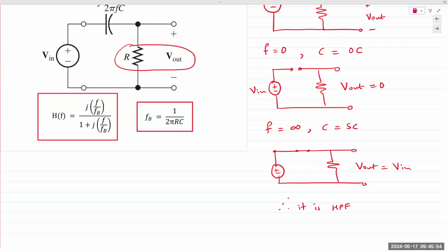And so if you want to send lower frequencies to a particular set of speakers, you would insert a circuit like this, a resistor and a capacitor, and the output across the resistor goes towards the high pass, and the output across the capacitor goes towards the low pass. So these are the two RC filters. Again, it's not a too complicated circuit in terms of analysis.